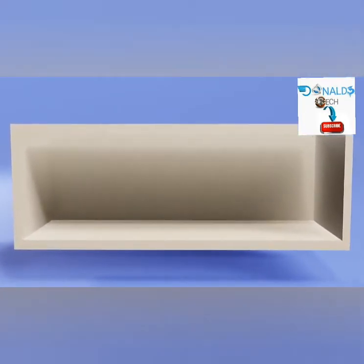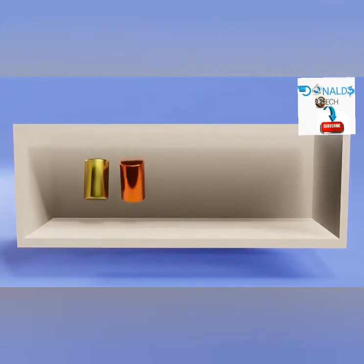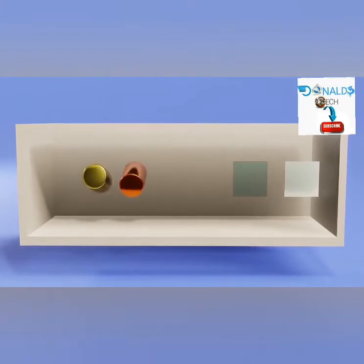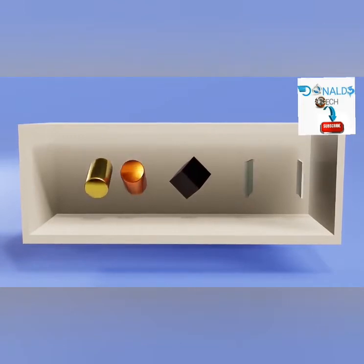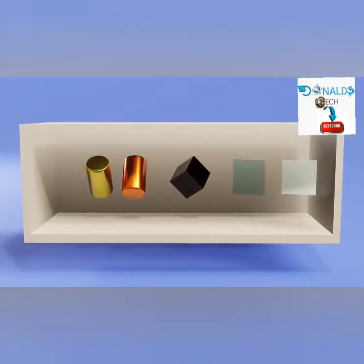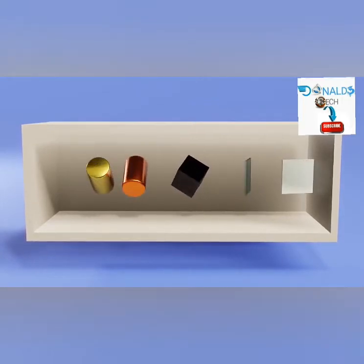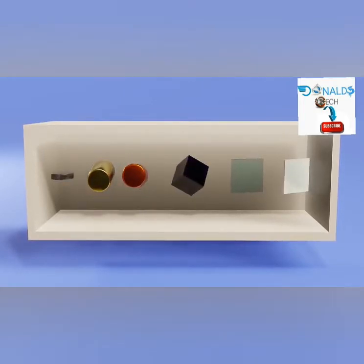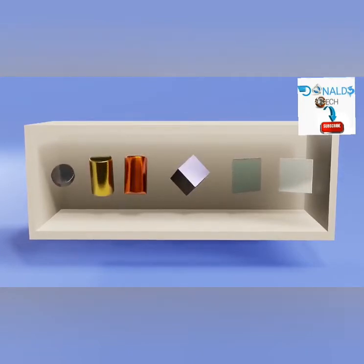If a material has a low coefficient of resistance, it is said that this is a conductor, such as copper or gold. On the contrary, if its coefficient is higher, it is said to be an insulating material such as glass or plastic. But there are also materials with intermediate values, and these are known as semiconductors, which, in some cases, vary their conductivity depending on other external factors, as we saw in the previous video about diodes. And finally, although they are an extreme case, there are also superconductor materials, which when they are below a certain temperature decrease their coefficient of resistance drastically.